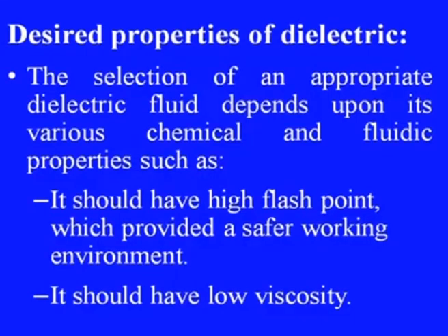Then it should have low viscosity, so that it can flow very easily as well as flush away the debris produced in that working zone. It should also have higher dielectric strength to minimize the DC arcing, direct current arcing, that takes place during that process.